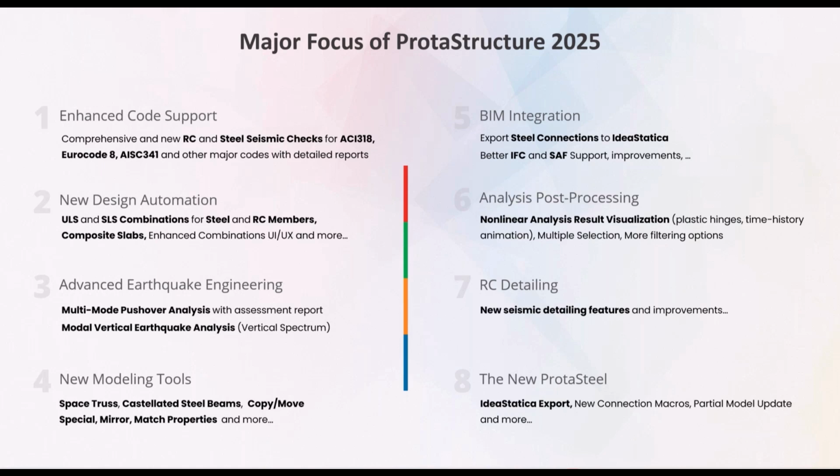In terms of analysis post-processing, we can visualize the nonlinear analysis results. What I mean by that is you can now see the plastic hinge formation, you can see the earthquake animation, and also you now have more control over the analytical model by filtering the selected parts. And also we have seismic detailing improvements, and new features in ProtaSteel with new connection macros, again the IDEA StatiCa exports, etc.